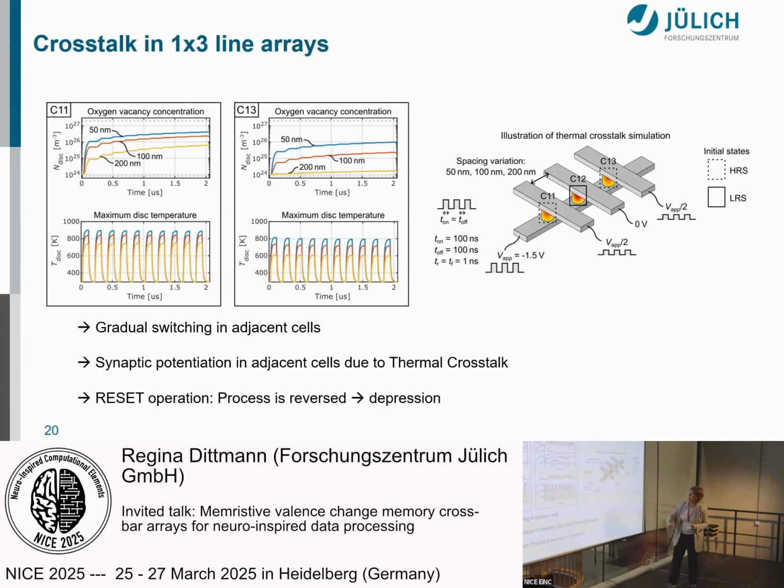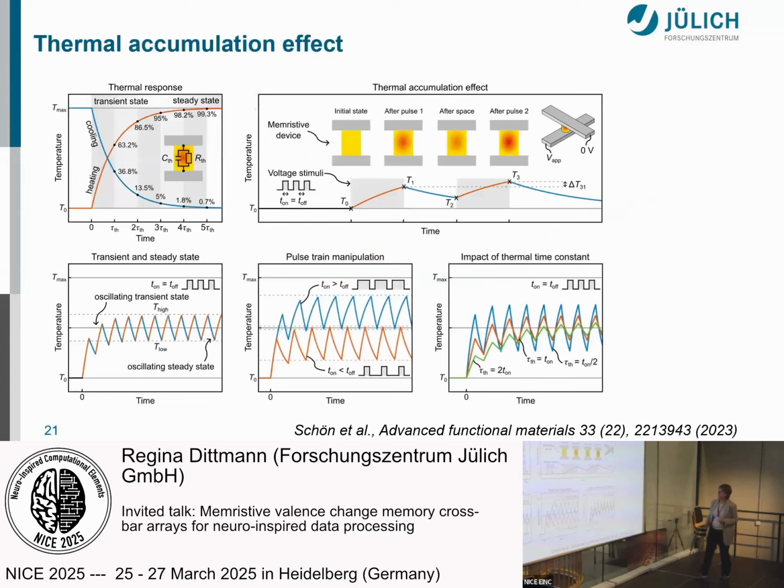And you can see here that during the pulsing of the selected memristors, you get considerable heating during these pulses in the two surrounding memristors, and a considerable increase of the oxygen vacancy concentration in the devices.